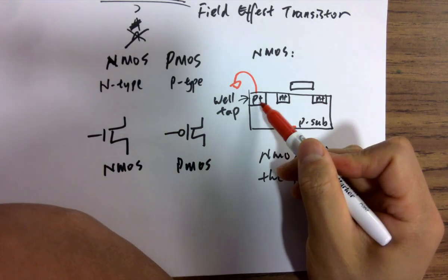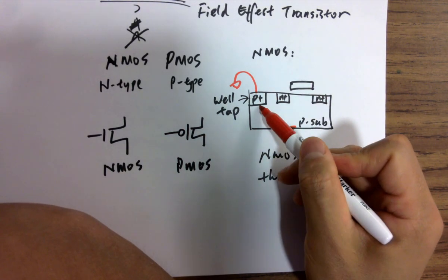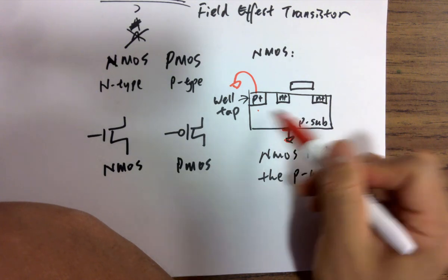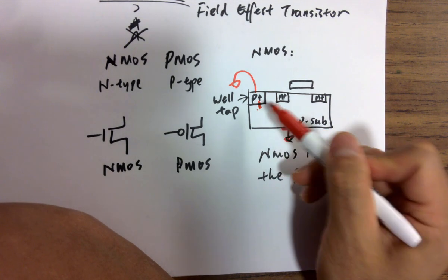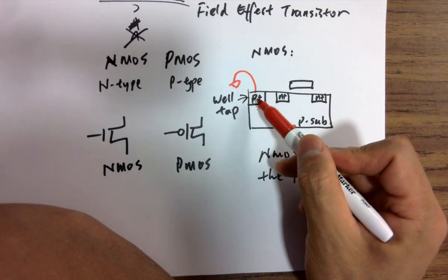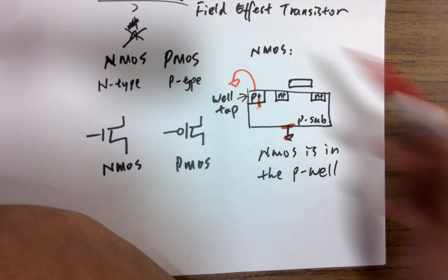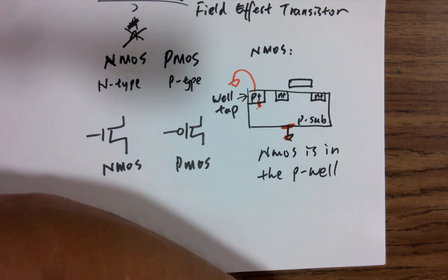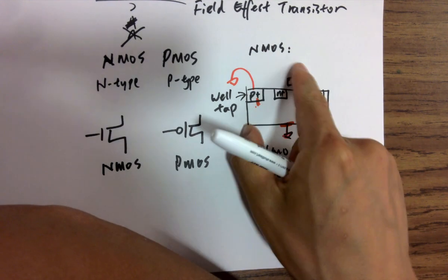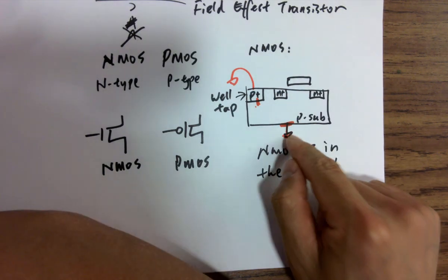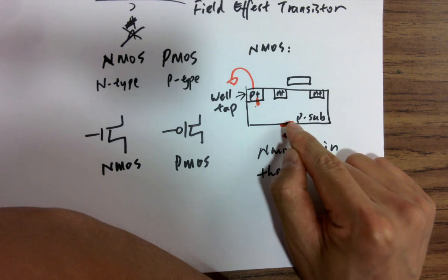Have a more conductive little piece here, and just implant it into the general P. It makes a connection here, and then you short this one on the top. You have all the metal layers, and eventually it goes to metal 3, which has an opening and shorts to ground. Or you can have this wire go to metal 1 and connect to the universal ground circuit, but not at the bottom.